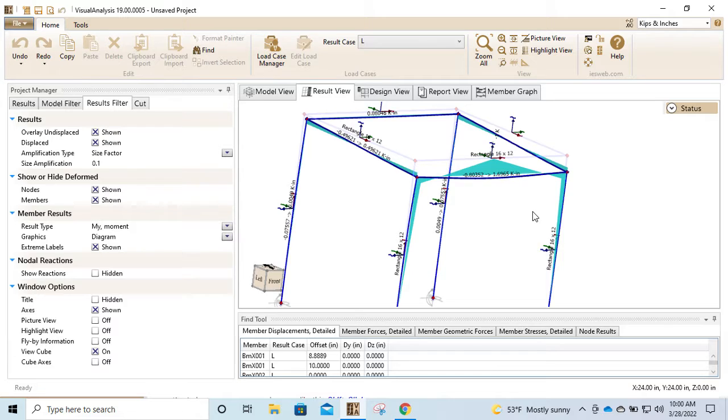But I want the sequence, right? The finite element analysis approach, which would be local to global, back to local. We start with our stiffness matrices that we developed in class, for the local level, and you have to assemble it based on the elements. All that sequence needs to be there.